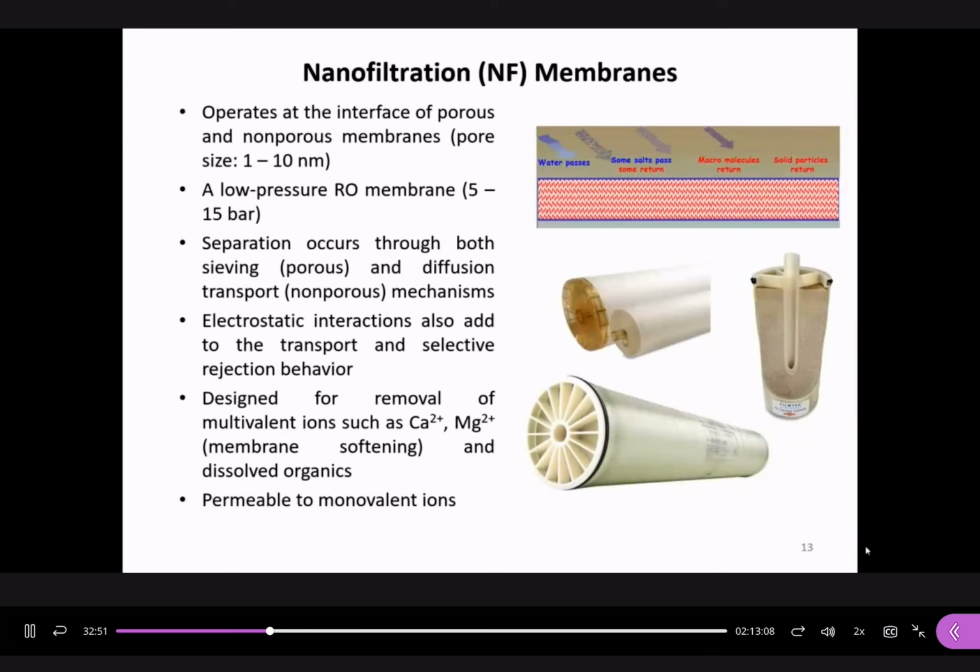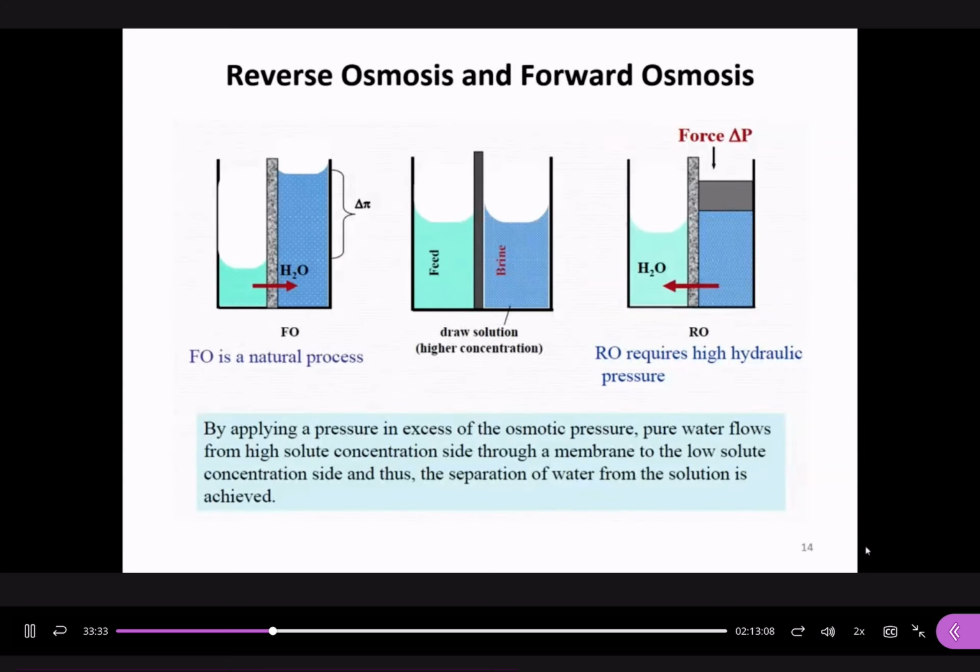Some typical nanofiltration membranes in the market have certain rejection for sodium chloride, probably 40 to 70%. It's not 100% through. Only probably 50% through. It can also reject 40 to 60, 70% sodium chloride. Okay. And finally, the densest, the smallest pore, reverse osmosis. I believe you have heard of this many times, reverse osmosis.